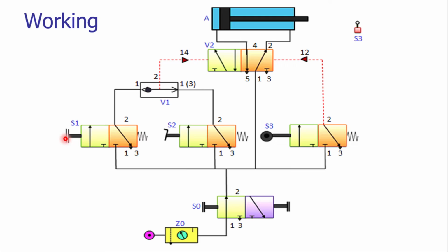So consider the push button is actuated. The default position of the push button valve is this. Here the application port is connected to the vent and the input port or the power port is shut off. There is no input at this stage. This is spring loaded.